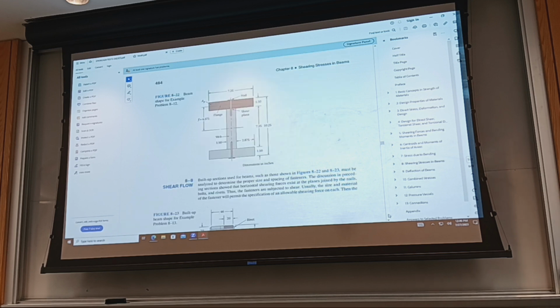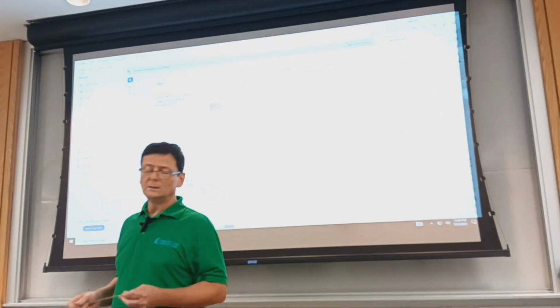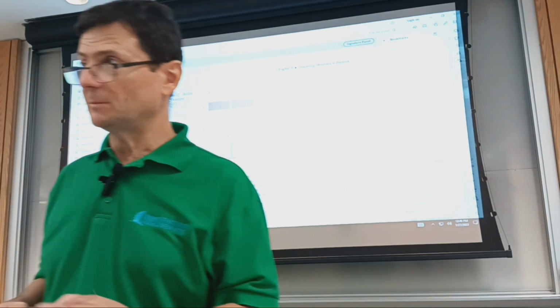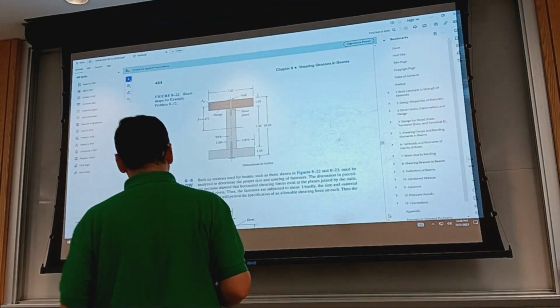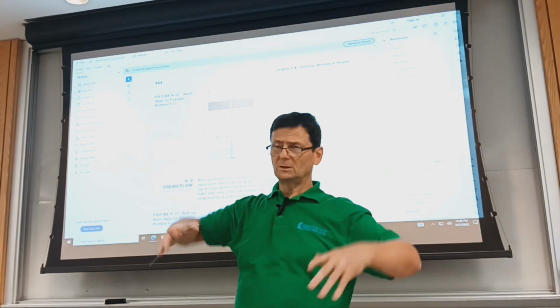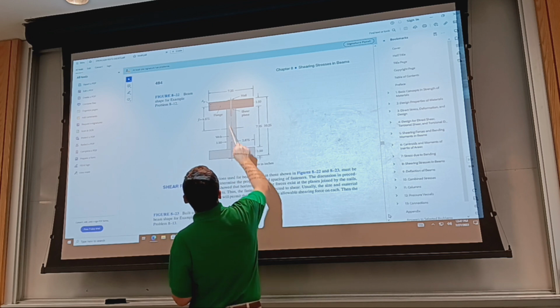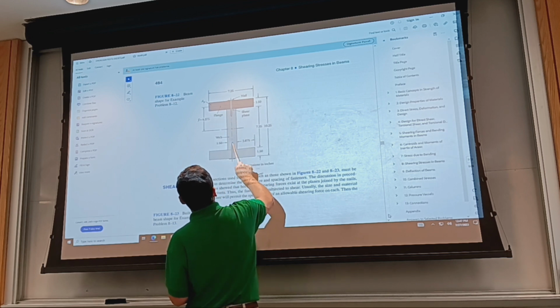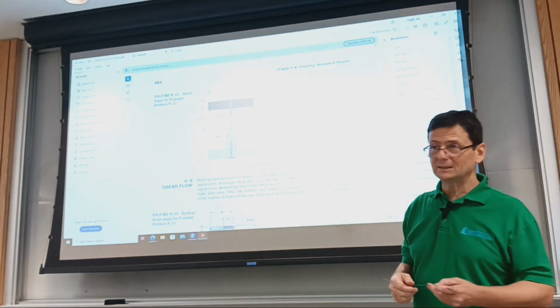All right, let's look at this concept of shear flow and how you can size fasteners. I said that you can see fabricated sections. I gave you the example, pretty common. If you drive by a construction site and ask permission, or maybe after hours, you can just walk through to see how they put together 2x4s to make beams supporting the attic, the roof. Or a full I-beam, you use three 2x4s, assemble them, and drive nails. The question is what should be the spacing of the nails.